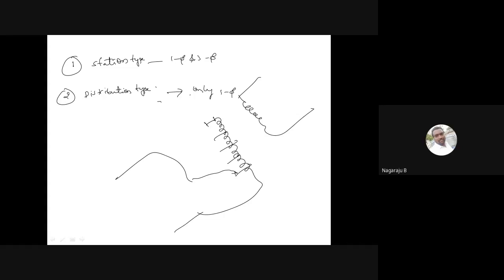The voltage regulating relay, also known as a contact making voltmeter, is connected to the output side of the regulator, which is associated with the line drop compensator. And the ratings of the regulators are based on their nominal voltage classification and their percentage of voltage regulation.